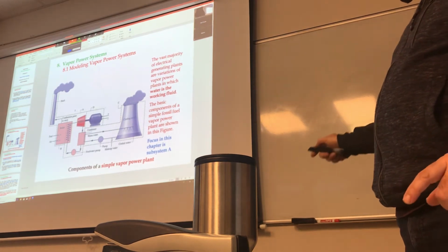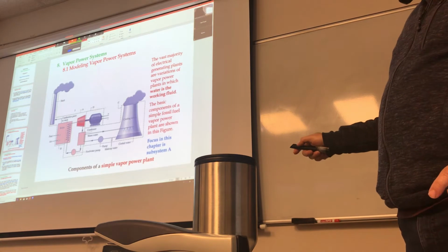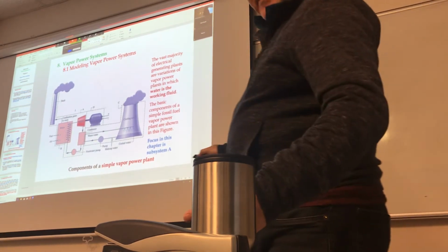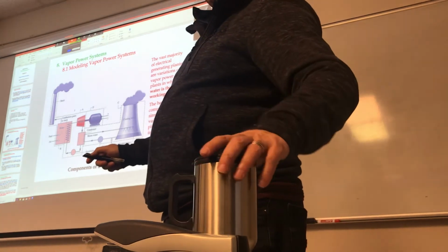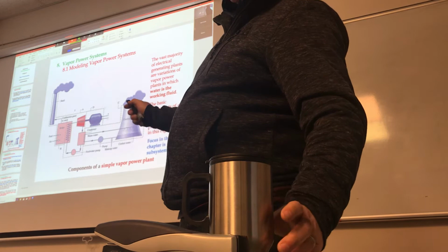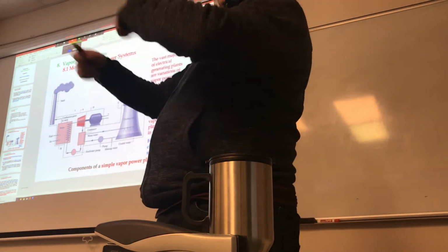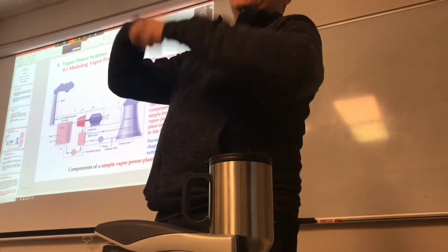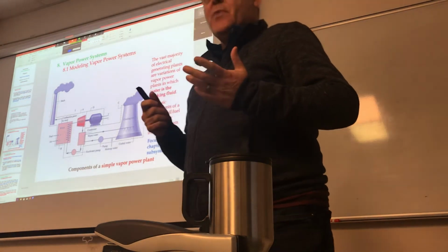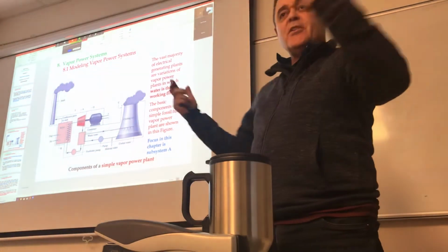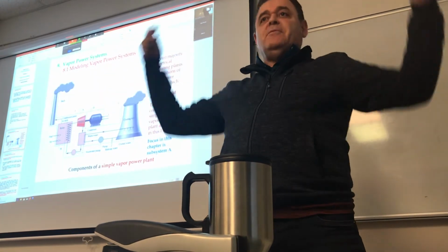Why would you throw away that energy in the cooling tower? This is kind of a tangent. Well, that's what exergy is all about. You can use it for many things. It just seems wasteful. Well, we will see that sometimes we reroute things to preheat some stuff instead of throwing all of it out, okay? So that's why exergy, I think, is important to understand, because you've got stuff that is hot, that has a lot of thermal energy, that is going out to the atmosphere.